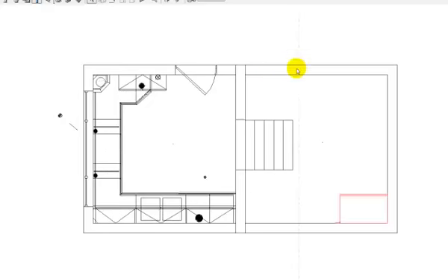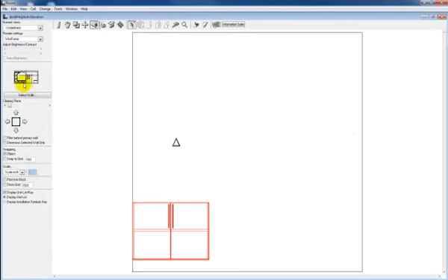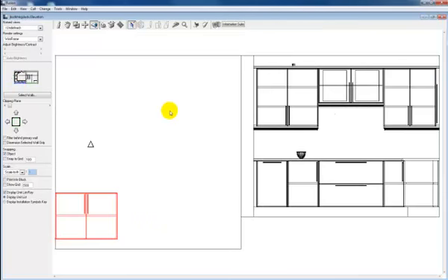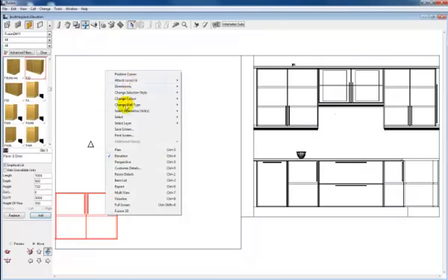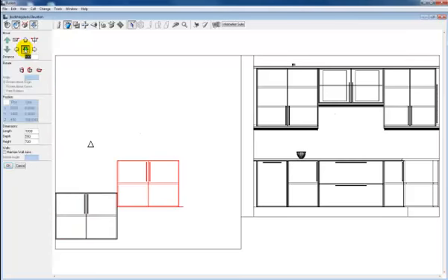If we add that, look in elevation, let's just select this wall here, it will add it into the correct place. We can just select a secondary wall there. The other method is to, let's just attach our cursor to the floor 2 door and add another one, add the units in, and then manually move them down to the correct position.